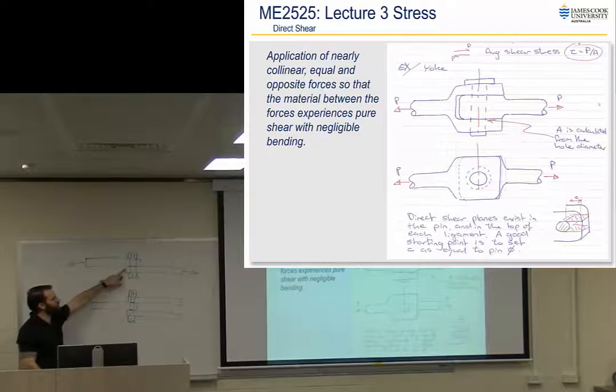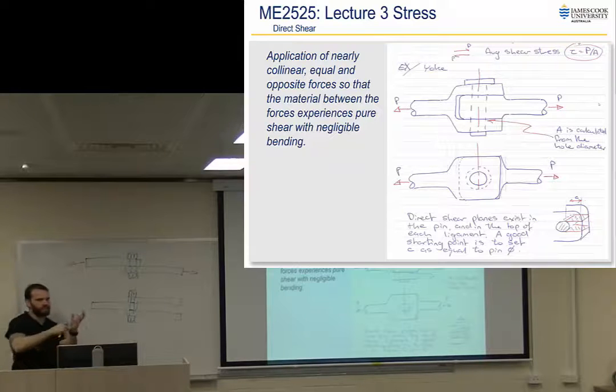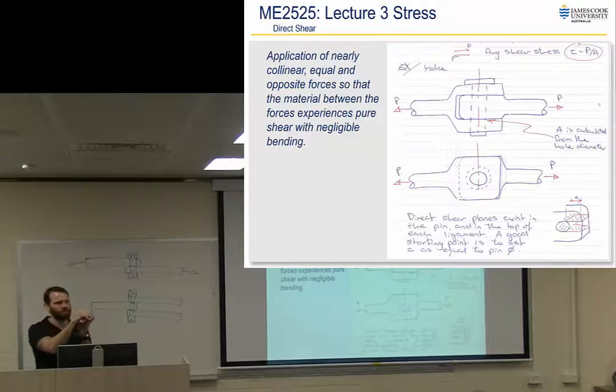The other thing with single shear, think about bending. All right, so it's not just shear that we're dealing with here now. If you have uneven asymmetric loading on a bolt, pin, or any other thing, this thing is now starting to tilt like that. And it's got sort of oblique loading and potentially tensile load as well as that shear, and everything's going very poorly for the bolt. All right, so that starts to become a much more complicated case, and if you only analyse it for the direct shear there, you might be missing half the story.